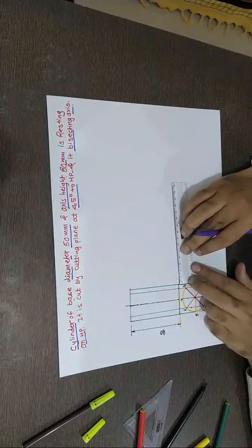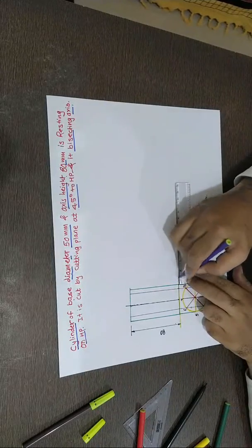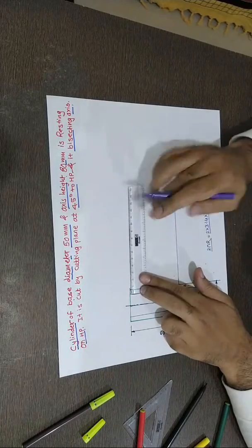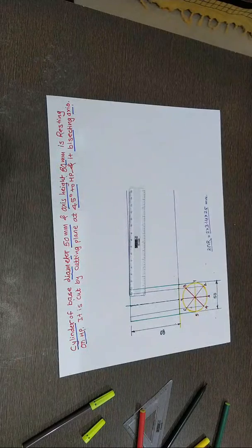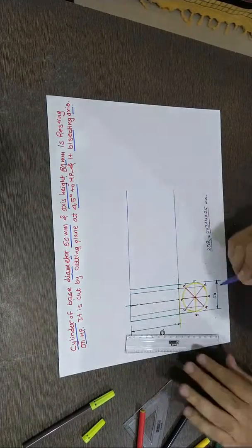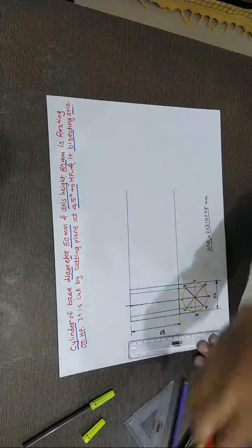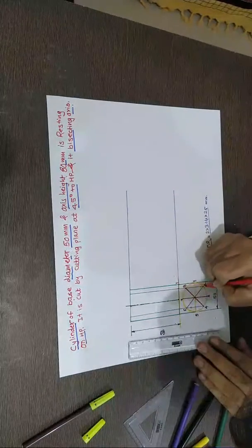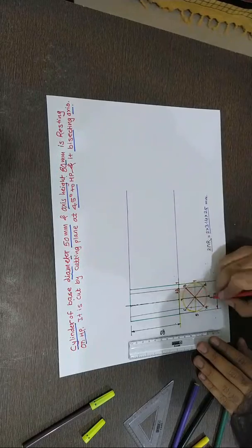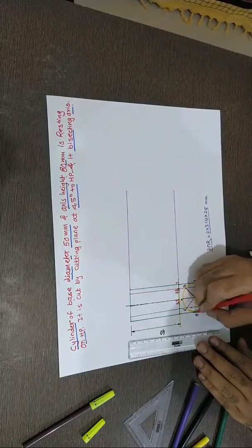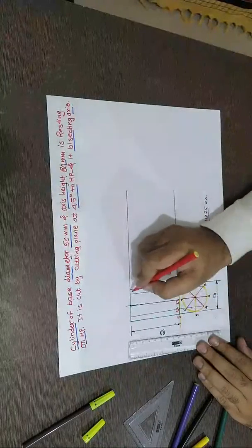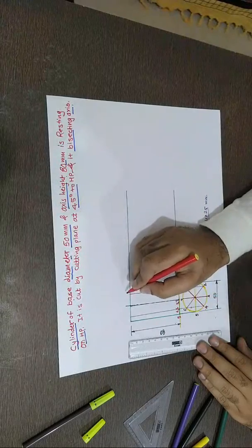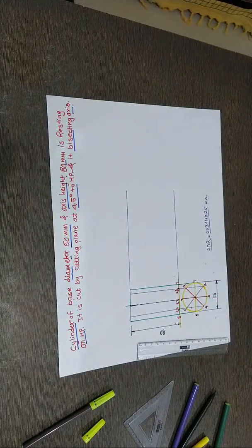So now let's draw a development. This is a point. This generator is passing from this 1. This is 2, 8, 3, 7, 4, 6 and this 5. If you want, you can give the same notation here, 1 1 dash, 2 2 dash, 8 dash. That's just to show and have a neat and clean drawing.